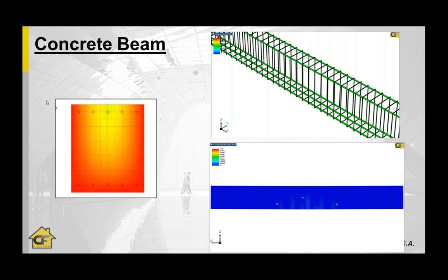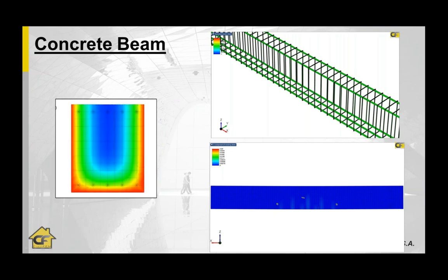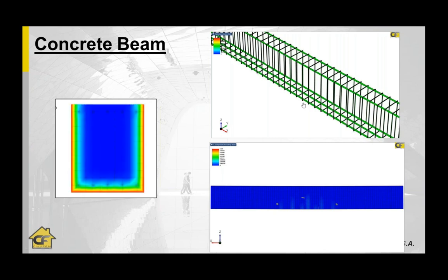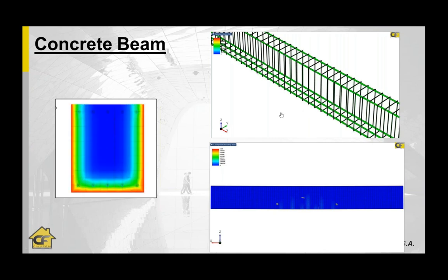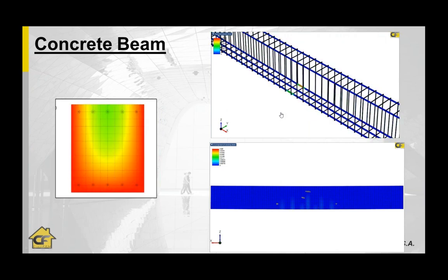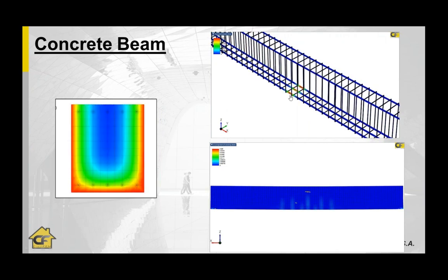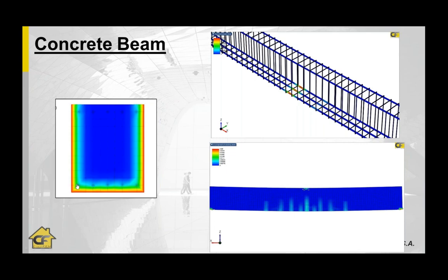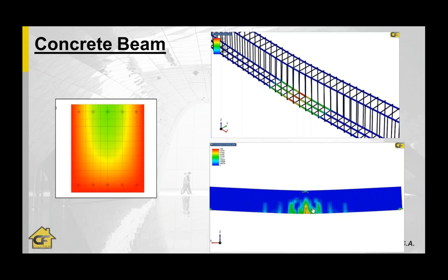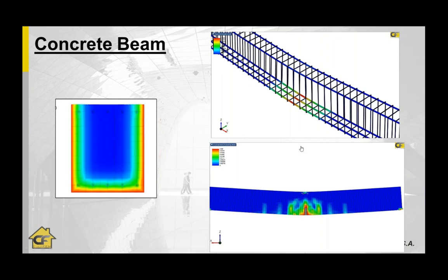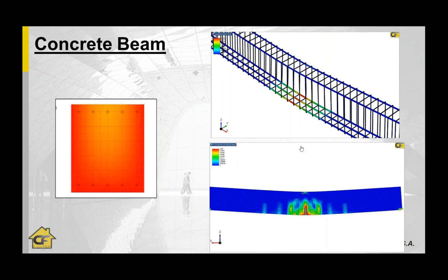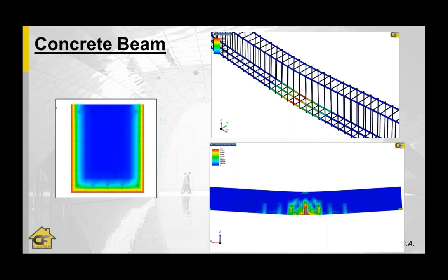On top of this, there is no fire; it is only applied on the lateral faces. And these are the results with the cracking and yielding on the model. So we can see that due to this fire, yielding starts happening on the model when the temperature reaches the reinforcement, and cracking is also happening until the collapse of the structure. So we obtain the time for collapse of this structure, which was about 210 minutes.